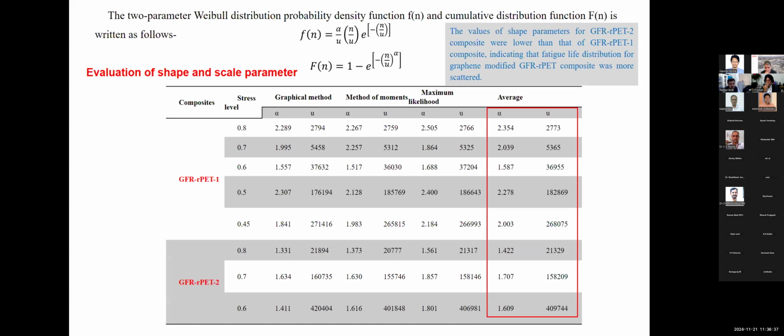We are already running on time now. We are 5 minutes over 4 o'clock. So I'll try to sum up here that fatigue damage or fatigue behavior of fiber composites is quite different from that we observe in the case of metals. The basic terminology remains the same, but the damage modes are completely different, and that is why they need a total review of what we study for metal fatigue. Weibull distribution can be used for both cases, but obviously the scale and the shape parameters will vary.